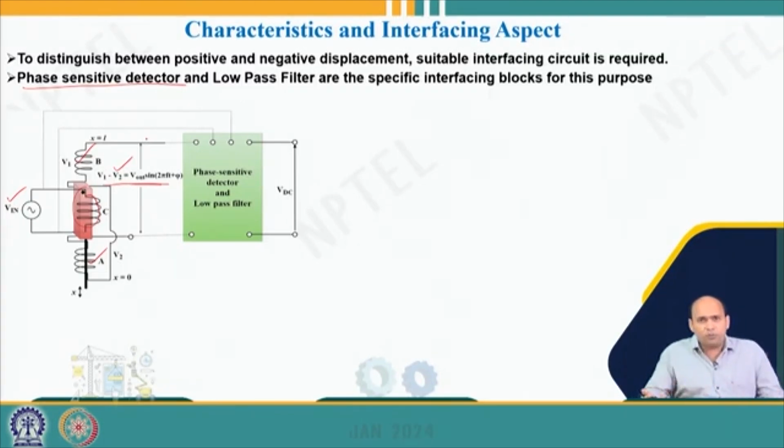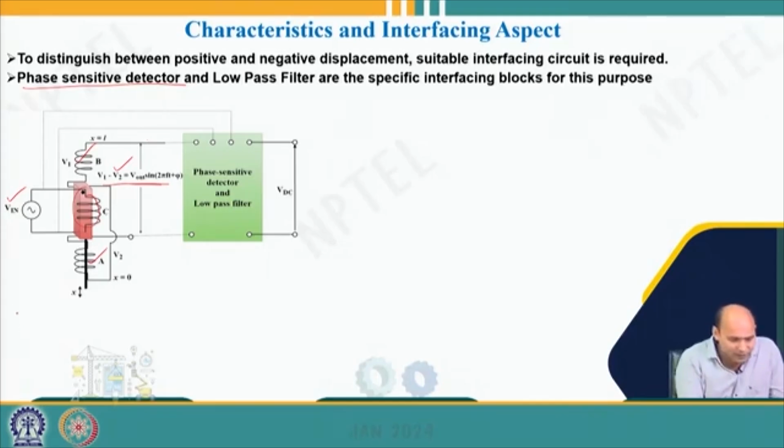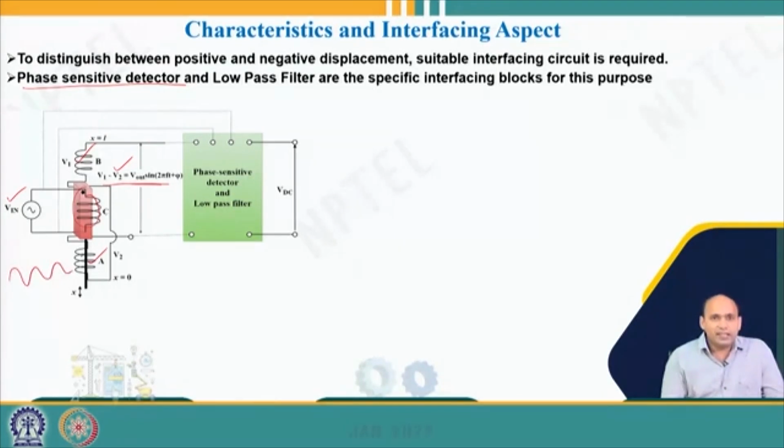So if I look at any AC waveform in some oscilloscope or some waveform measurement device, you cannot distinguish by looking only at the waveform, you cannot understand what the phase is, right? Because in both the cases it will look like this kind of sinusoidal thing, is not it? In order to distinguish the phase, you have to compare two signals, then you can understand.